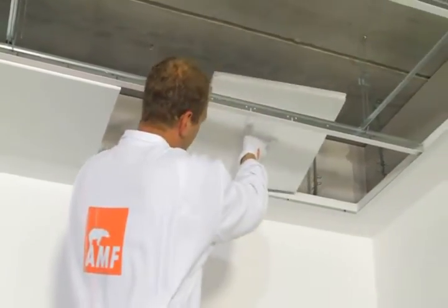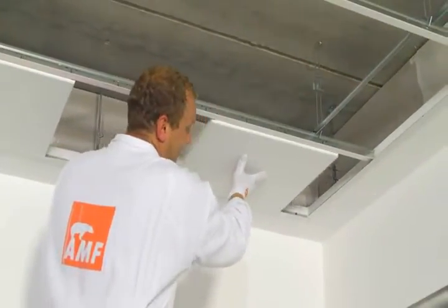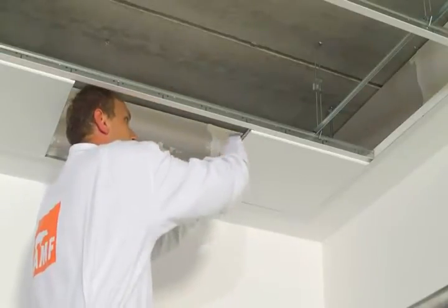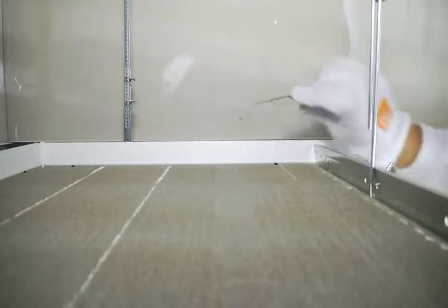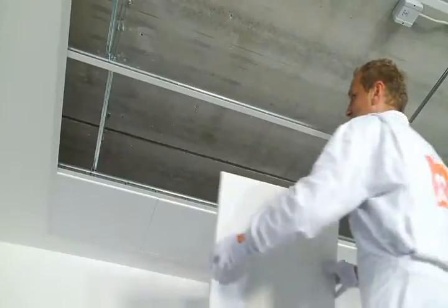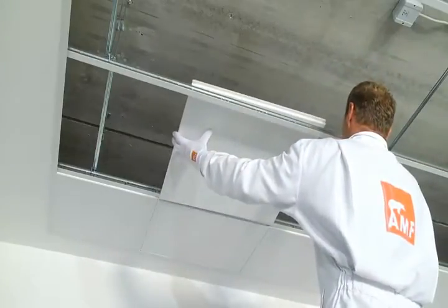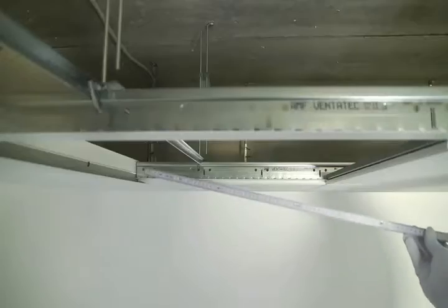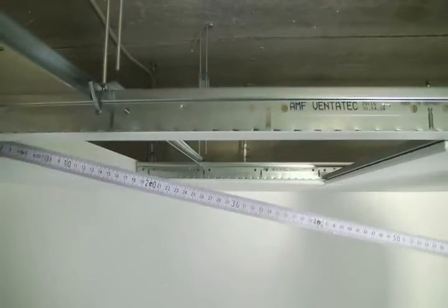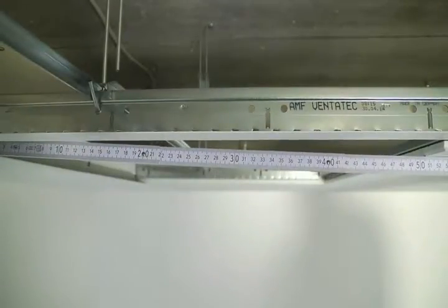The corner tile is not cut exactly to size on the short side, but is cut 10 mm smaller than the clearance between the penultimate tile and the wall. They are installed as the penultimate step and secured with a perimeter clip. The first full tile is then aligned and installed exactly in the second row. The distance to the wall is then measured at 2 points and the tiles cut exactly to fit.